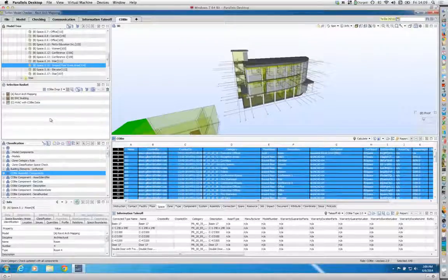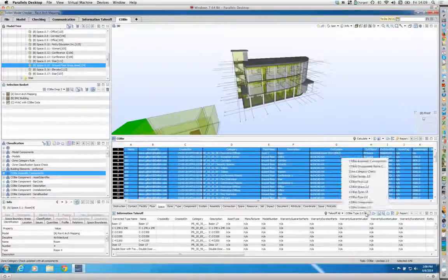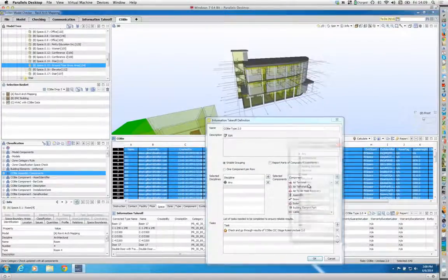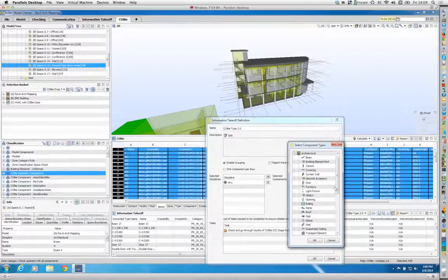You might only want to display, so pipe fittings wouldn't normally be included, or pipe lengths wouldn't be included either. The actual flow distribution devices would be, but the pipe fittings wouldn't. So you're in a situation where the list of IFC-based classifications isn't far enough reaching to be able to do it. So what it gives us the ability to do is we can go back into those settings, and I can add back in my walls here.